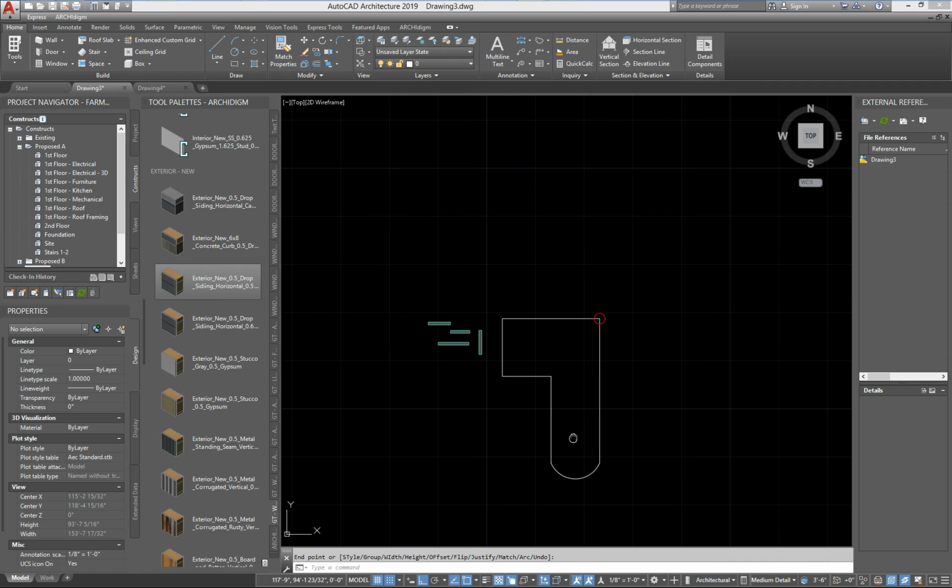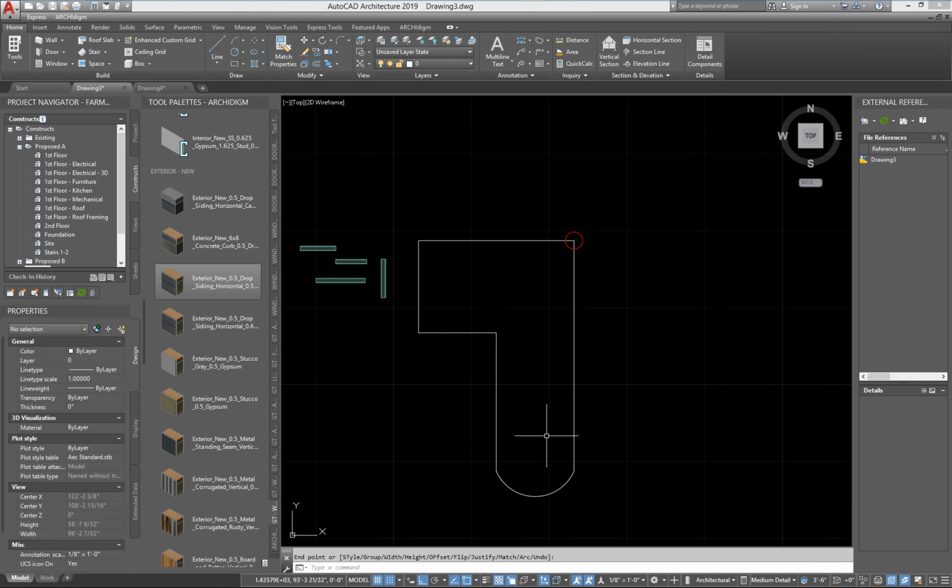Converting line work is particularly useful if you're doing as-builts, or if somebody else has given you an AutoCAD perimeter of a building, and you're going to be turning it into an AutoCAD Architecture building. Having a nice clean polyline is very useful. So now you have the choice of doing it off of a tool, which I prefer, but know that you can also type in WallConvert if you don't have access to the tool for some reason. WallConvert won't let you pick a style, which is kind of unfortunate, but it will work. So if I go ahead and do this and hit enter,